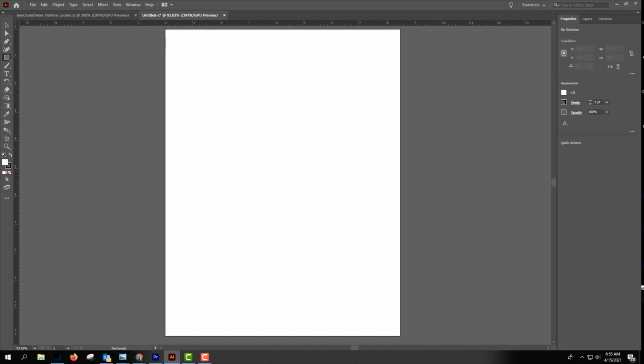Now you can see that the ruler changed. When I go to make my box, I click one time and I have inches. I could also have just typed in IN, and that would have changed the units for that specific object. Right now the width is 2.5 inches, and for the height, you can do the math if you'd like, but 3/8 of an inch is 0.375, so I want it to be 1.375, and boom, there it is. So that's the size that I'm going to do.